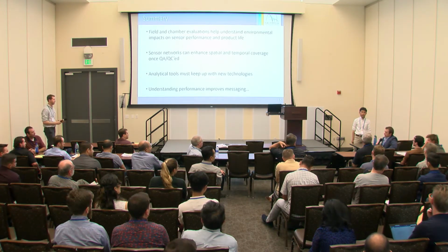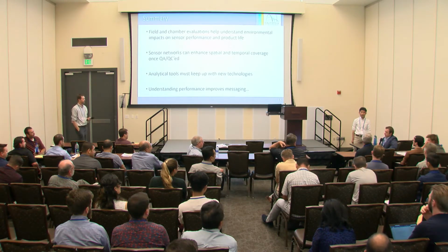Yeah, that's a good question, and I think that's kind of the scope of the program. We're a sensor performance evaluation center, not a certification center. So as things transition in the coming years from an evaluation center potentially going to standards, it'll definitely have to take seasonality into account. And that's one of the reasons why I filtered all the results at 50 micrograms per cubic meter, to try and even out that seasonality difference between the evaluations taken at different times of the season. The 2 months is a good time frame.